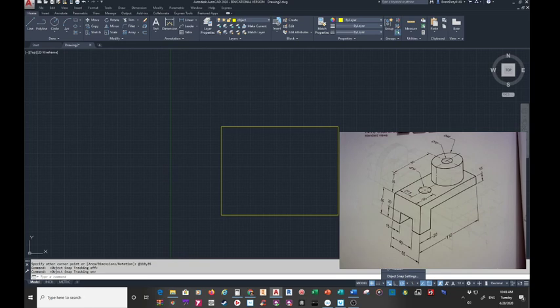So as a review, I only turn on the ones that I think are important. Some people tell you just turn them all on. Well, you can have too much of a good thing, in my opinion. And that's my opinion, and I'm welcome to have it, and other people can have their own. What I do and why I do it is these are the important ones to me: extension, apparent intersection, intersection, center, midpoint, and endpoint. Those you use all the time.